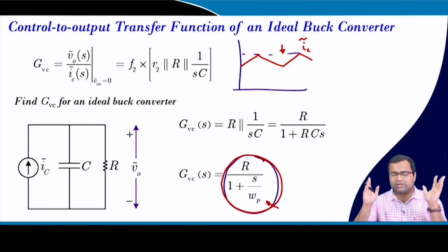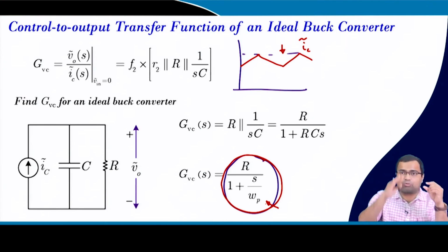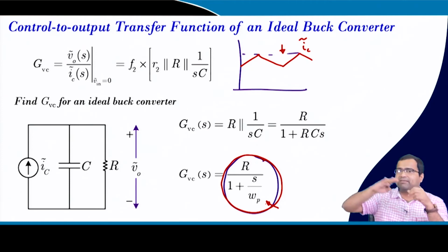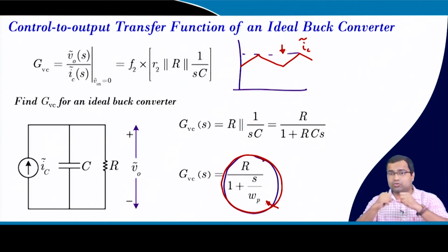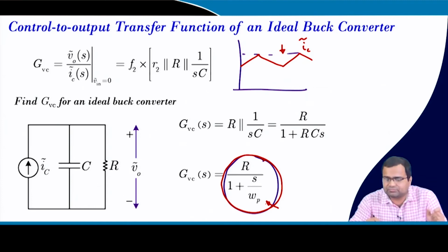If you go to lecture number 17, you will find the response after load transient becomes very sluggish, like an overdamped response, because it virtually behaves like a first order system, because you have made the current a control source. So, the inductor pole is as if you pushed it very far to the left hand side, and that dynamics is not coming into the picture.